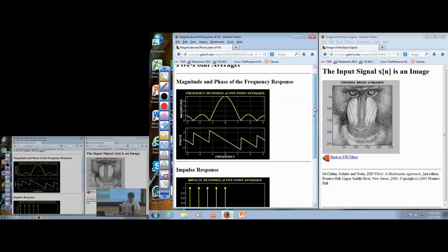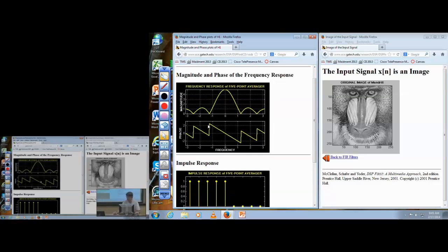If we look at the phase response, we're expecting a phase that is a line, and this phase is a line except at these points of discontinuity. These points of discontinuity line up exactly with the zero locations in the magnitude response. So these frequencies at which the discontinuities occur do not pass through the filter. Why the discontinuities occur is the following. The frequency response, or the Fourier transform of the impulse response here, which is a rectangular pulse in the time domain, is something that looks like a sinc. The sinc would normally follow my mouse here, and since it's a magnitude response, we take the absolute value, so the negative part kicks up to be non-negative, except for the two zeros. This sign change around the zero crossing corresponds to these discontinuities of pi in the phase response.